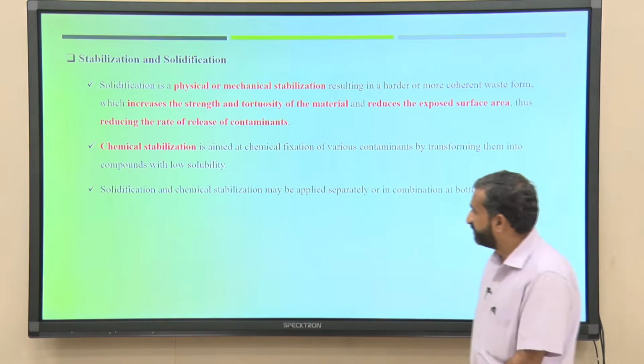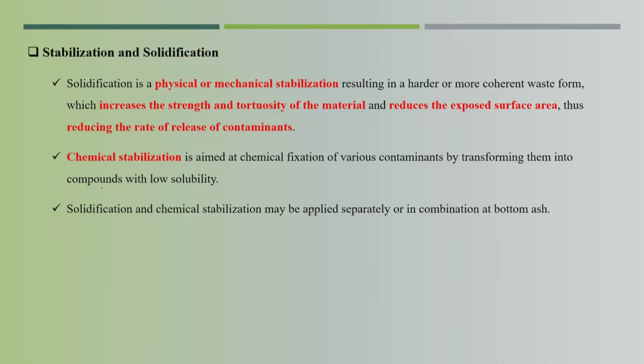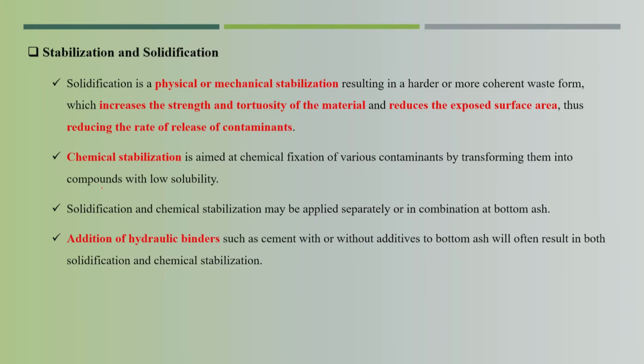The solidification and chemical stabilization may be applied separately or in combination for bottom ash. Also, the addition of hydraulic binder such as cement, with or without additive, to bottom ash will often result in both solidification and chemical stabilization. So, this is also one of the benefits.